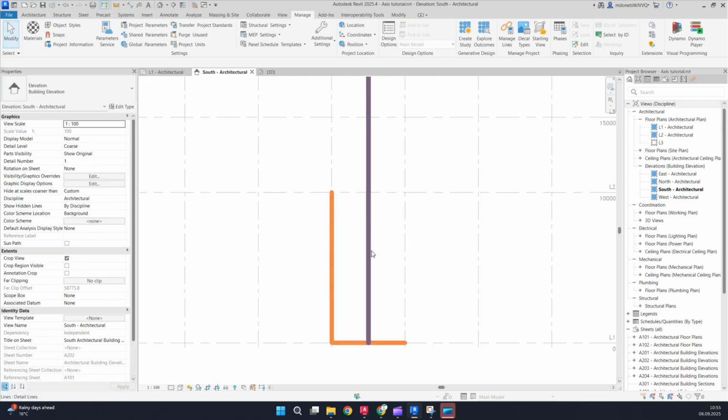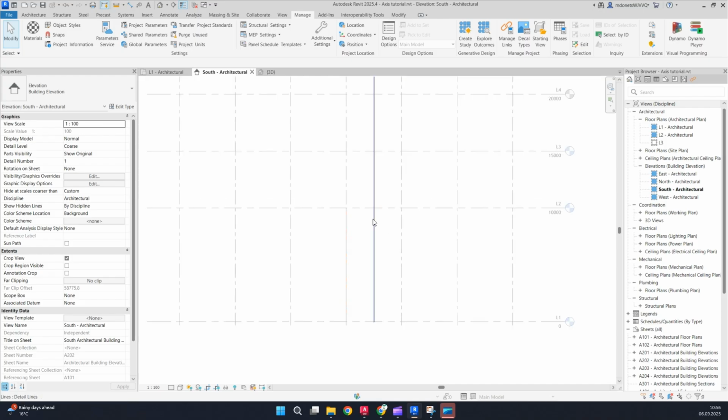By default, your lines will be extra thick. But to work with it, you can just turn on the thin lines and all of the lines will be the same thing. But you need to keep in mind that those lines will be thick when you're putting them to print, so you will need to change it after all.